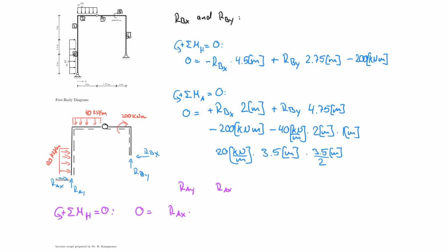times, I need to be careful, the height of that leg of the frame, which is effectively the distance from here to here. So that's 3 plus 2 plus, so 6.5. So times 6.5 meters. And it's turning counterclockwise, so therefore it's positive.